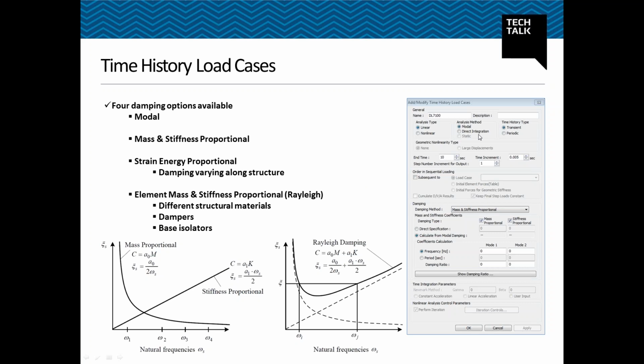Before moving on, for the time increment, it is recommended to use 1/10 of the period of the highest mode for the initial value of the time increment.